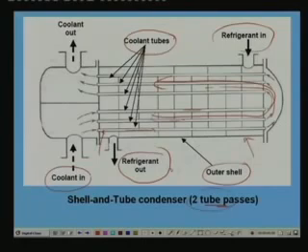of condenser. Okay. So, as the refrigerant vapor comes in contact with the coolant through which the coolant is flowing, again heat rejection from the refrigerant takes place. So, refrigerant condenses and the condensed refrigerant again collects at the bottom of the shell. Okay. And finally, this condensed refrigerant leaves from the bottom. Okay. Typically, whenever you are using shell and tube type of a condenser, this refrigerant goes to a receiver from where it goes to the expansion device.